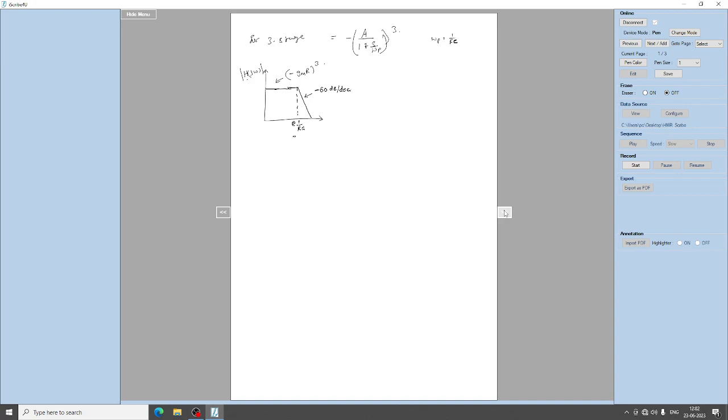At this point we have 3 poles, right. So this is your gain plot. This is how your frequency response will be, the gain response of the 3-stage RC circuit. Okay. So now if you look at the phase, that is the angle of H of j omega, with respect to the frequency.